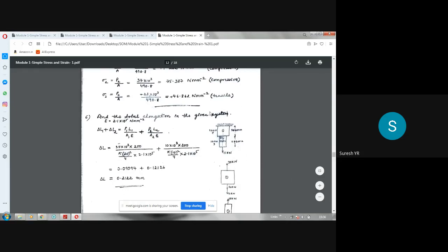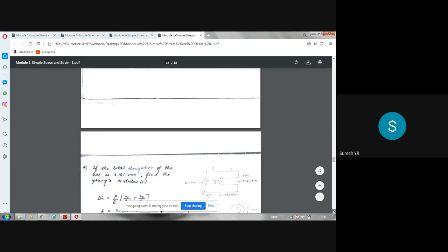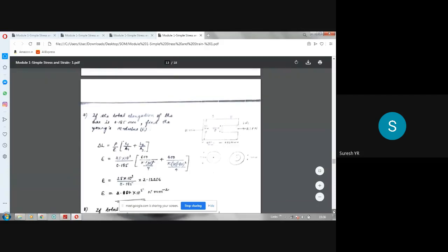So here, hanging bar. In the case of a hanging bar, the same procedure is used. When you want the total deformation, it is the deformation of this portion plus the deformation of this portion. So instead of being given horizontally, it has been taken vertically, that's all. You can study this problem yourself, similar to the last problem. You have to take the two portions separately.